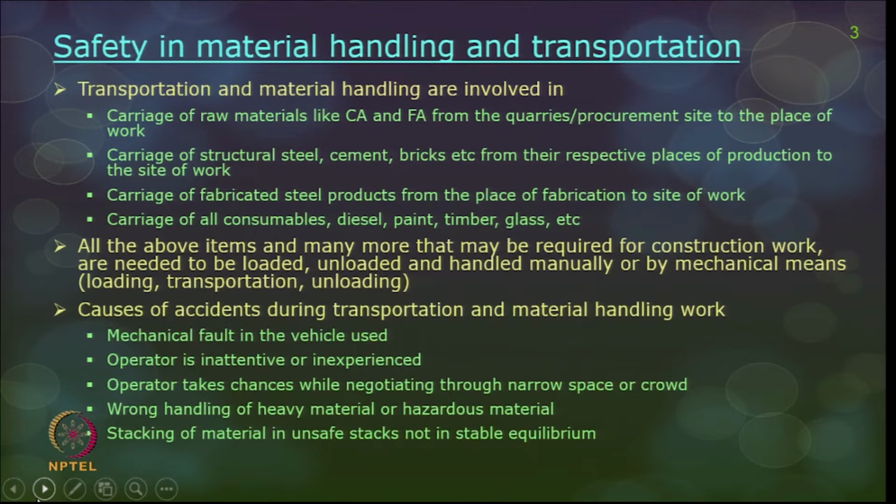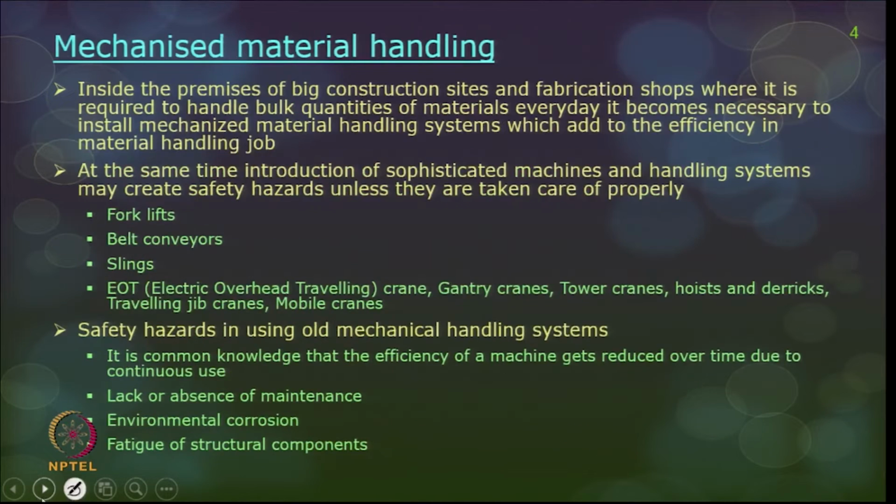Mechanical fault in the vehicle, operator is inattentive or inexperienced, operator takes chances while negotiating through narrow space or crowd, wrong handling of heavy material or hazardous material, or stacking of material in unsafe stacks and not in equilibrium. When you are piling up the material, it should be tapering on the top. You have to pile it up like that, so that it is not falling off, or it should be towards the center and the equilibrium has to be maintained, so that it will not be staggering and falling down.